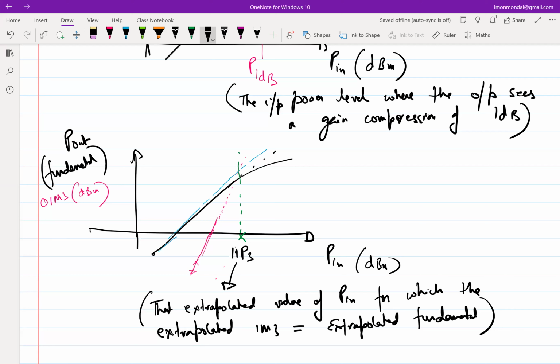But just like anything else, you need to understand in a short way whether the system is linear or not, how linear it is when you compare two systems. So when you are talking about third order distortion, if you have two systems with certain IIP3 numbers, clearly the one with the higher IIP3 number will be more linear than the one which has a lower IIP3 number.